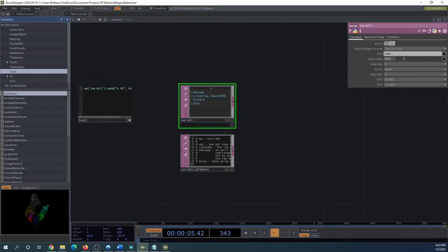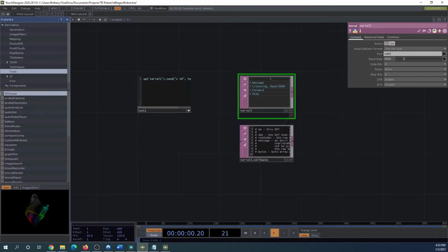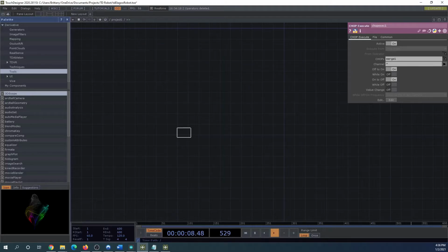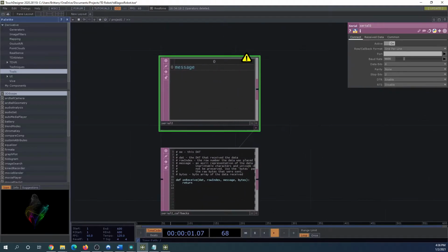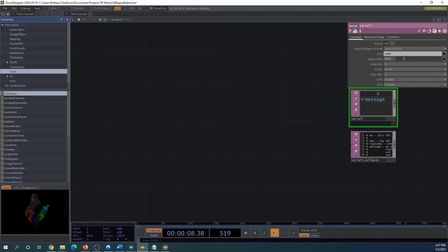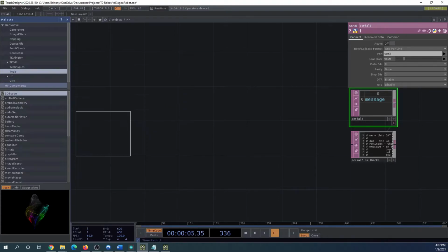So now let's do the fun part. Create a controller via TD. So all you need to build this is get a serial DAT again, set the COM to 3, I'm going to leave it off for now, and then instead of a text DAT we're going to grab a comp button.